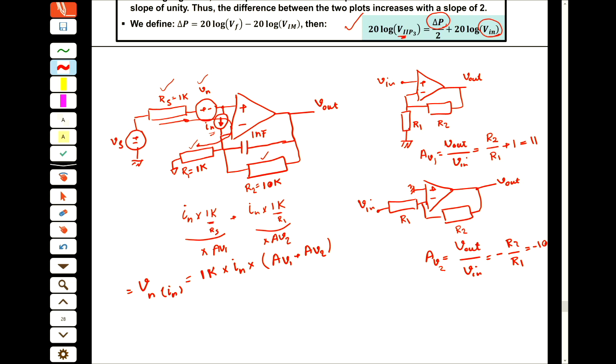You can follow there. I just want to tell you how we should look at each component. These are the different sources that we need to find, move to the output, and calculate. One more thing remains, and that is the bandwidth of this op amp. Remember that for the noise of a resistor, Vn squared equals 4kTRB, and this B is the effective bandwidth of your system. I mentioned at the beginning of this lecture that this is the effective bandwidth.